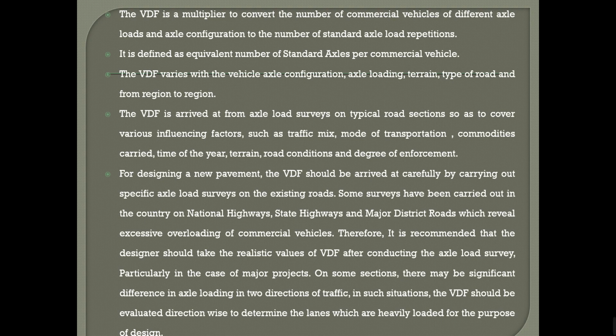Not other district roads, only these: express highways, national highways, state highways, and major district roads. These are of prime importance, where most of the transportation is carried out, or most of the traffic is likely to be running between origin and destination, carrying cargoes and loads between terminal stations. Now your road should be capable of withstanding the stress, strain, as well as deflection whenever loads of 8 tons or beyond come upon the roads.